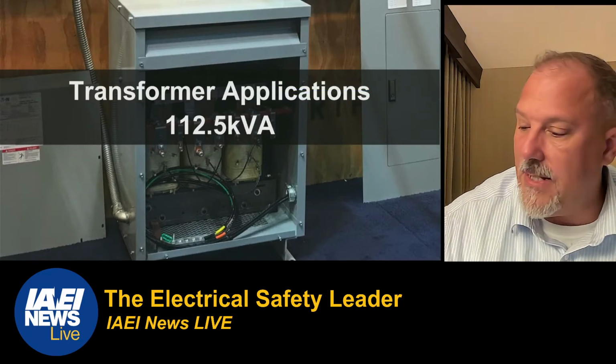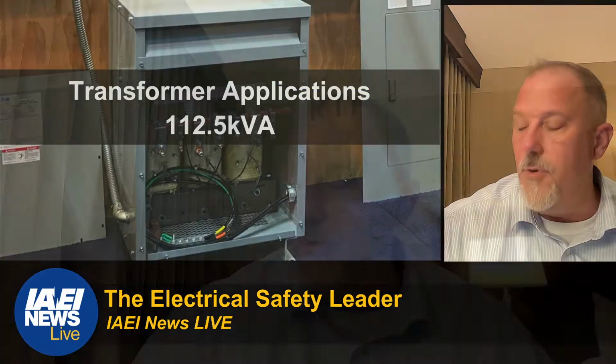So that's the transformer. We went through the selection of the primary and secondary overcurrent protective devices, and then the conductors. You're going to pick the conductors based upon the ampacity. I'm not going to go through that. That's a 310 exercise. You have a raceway. You've got to think about the number of conductors in a raceway, and if you have to do any adjustments of ampacity based upon temperature, etc. But you're going to pick the conductors for your primary and secondary equipment, feeders and transformer secondary conductors.